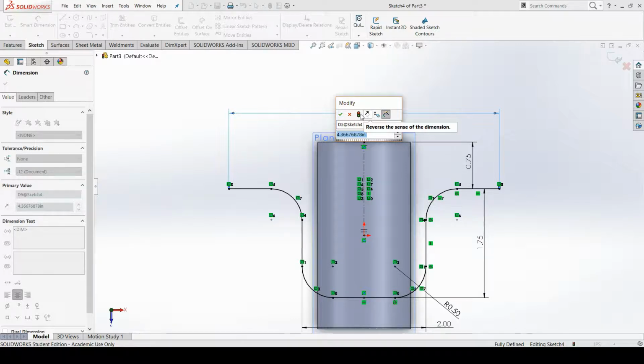So what we're doing here is we're setting a length from the very leftmost point of the sketch to the very rightmost point of the sketch to be equal to the circumference of the circle, or the total distance going around the circle. This is going to allow our sketch to completely and perfectly wrap around our cylinder, because as you know from our first video, our cylinder has a diameter of 1.5, and this pi value, it's a universal constant